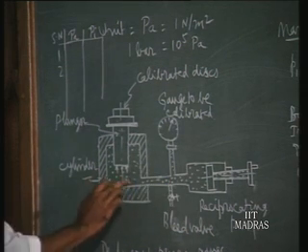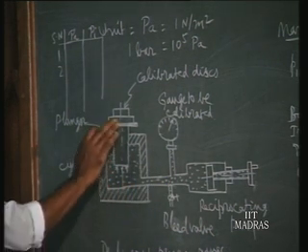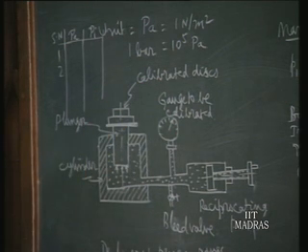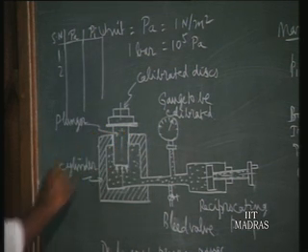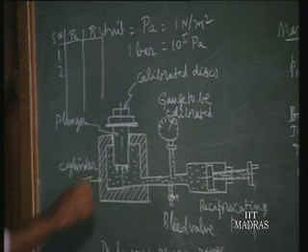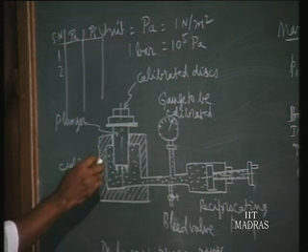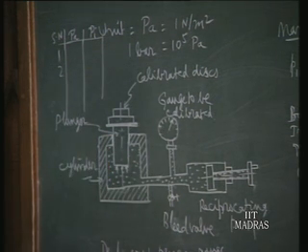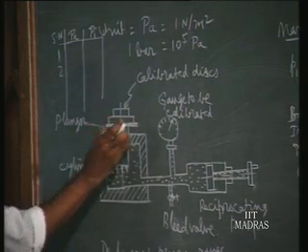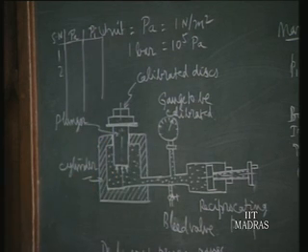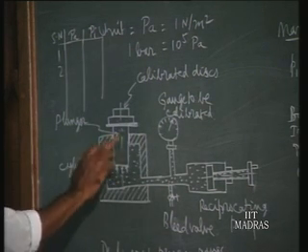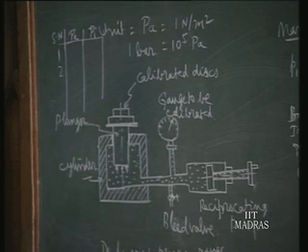So the pressure developed in this liquid is measured by balancing with the calibrated disc, and that is used for calibration purposes. The error source here is the static friction between the cylinder surface and the piston, and that can be made as small as possible. When we take measurements, just twist this piston plunger. As it rotates, the static friction is removed and only dynamic friction will be there, which will be very small. So that can be taken care of while we take measurements.